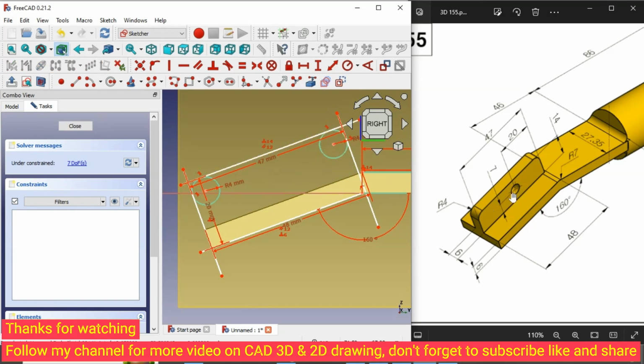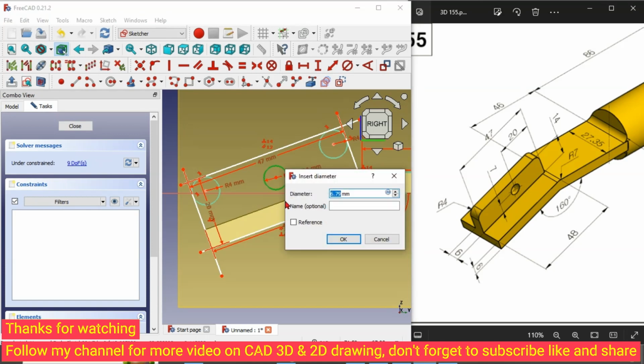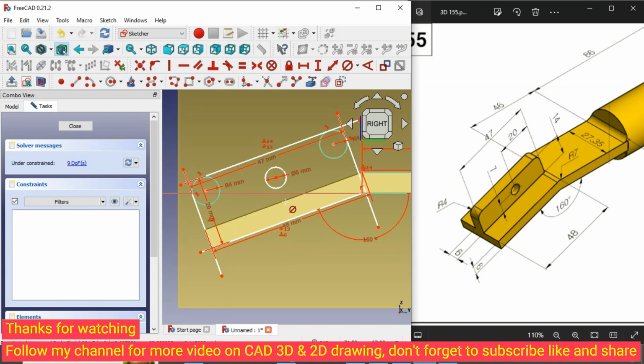Okay, we have another hole here. We draw a circle. Because it doesn't give any radius or diameter dimension here, I set it to be diameter, I just say 6. It should be okay.